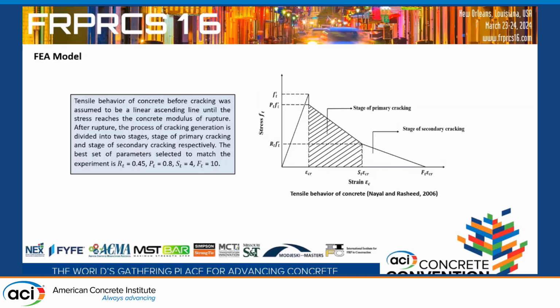For this model, you just need to know the tensile strength, and you can get all the points on this curve. All the parameters are listed, like R sub t, P sub t, S sub t, and F sub t, which is from the experimental results.